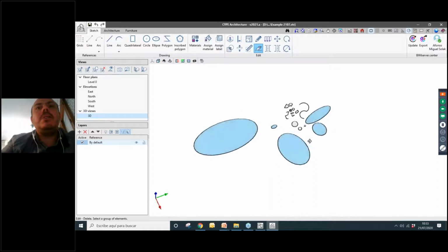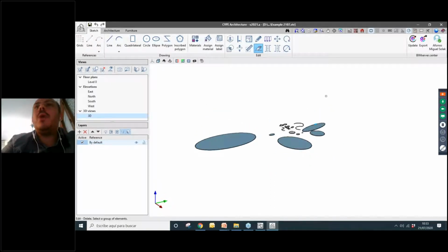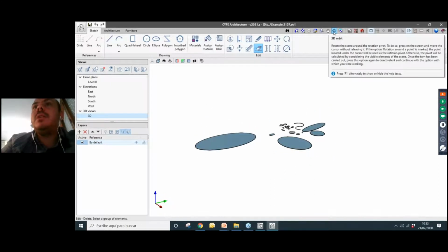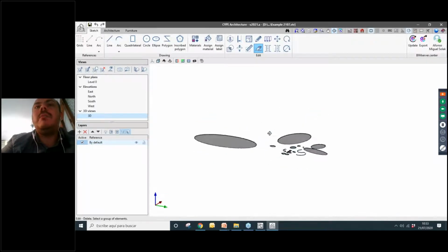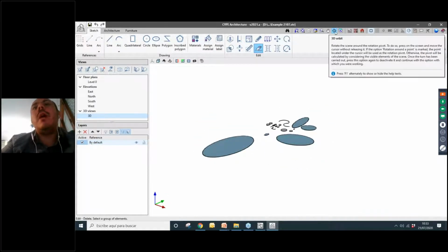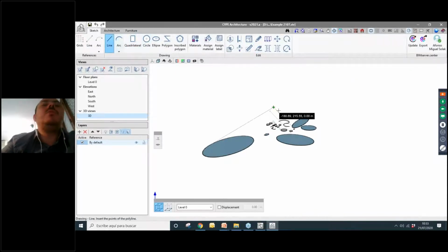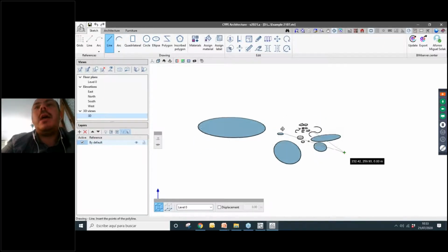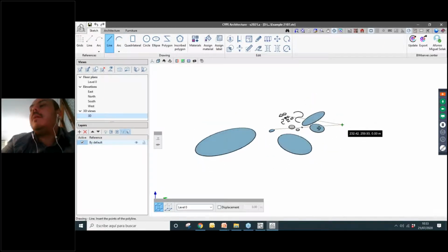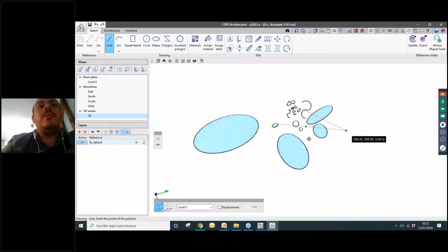We can do this effect, or we can use this little button here, the 3D orbit. So it's the same thing. When we click here, we don't have to press the shift button. But if you don't click here, you are using another tool. Just with shift and the roller ball of your mouse, you can do this movement.